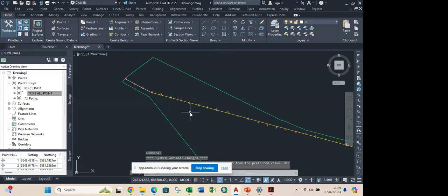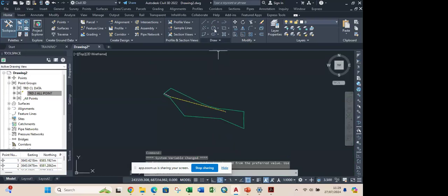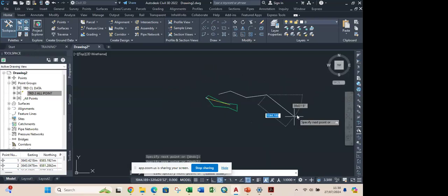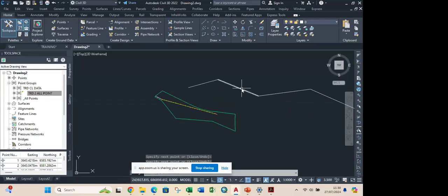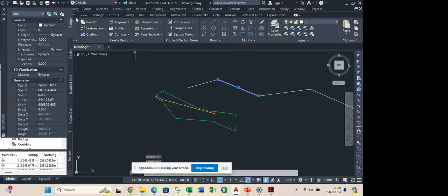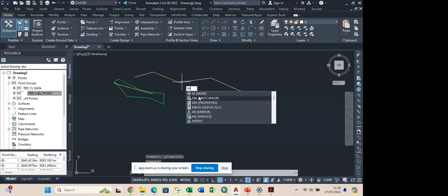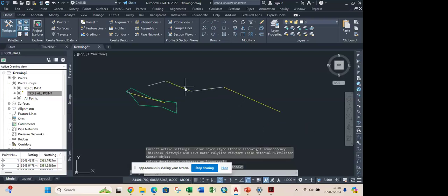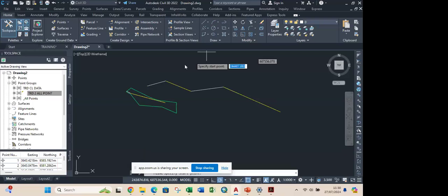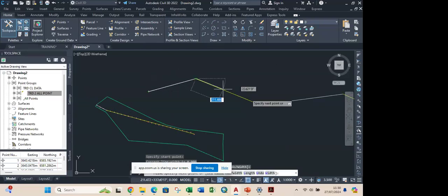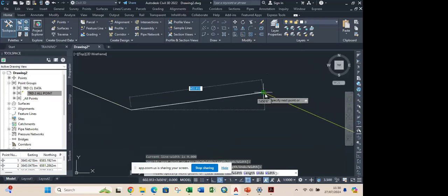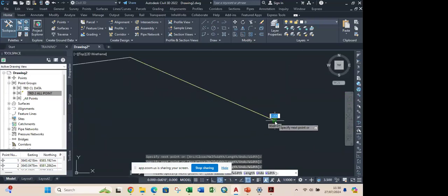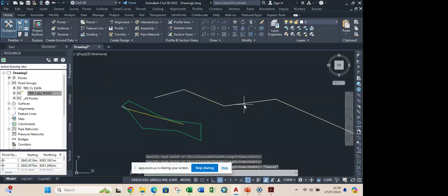So once I have this different coloration, imagine I'm having multiple lines like this. Once I give this one a different coloration, for the other one I would also do a match property command. Match this one and this one, because I will match them. Once I'm done matching them, I will pick a polyline. It gets me faster. I'll select this and go, so it'll be faster for me to trace across the line. That's the same principle I want to adopt here as well.